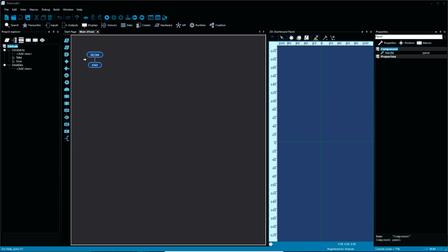So as I said, we want to blink an LED. We want to blink the onboard LED, which is connected to port B5. So, this is something we're going to be doing forever, so let's create a loop. Click on that, drag it to the window, and you've created a loop. While 1, so this is something that will continue forever.